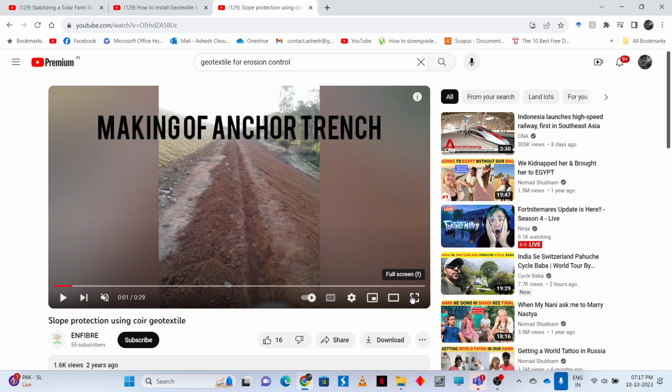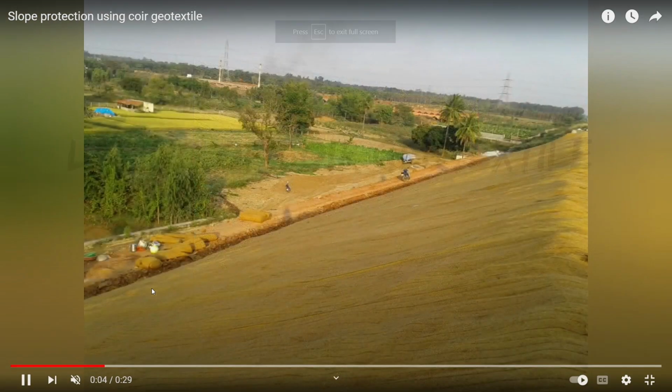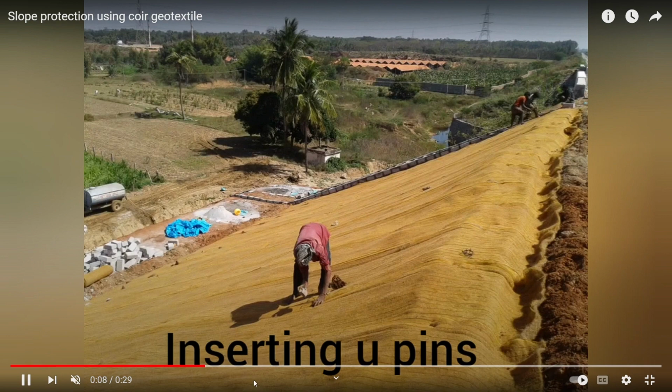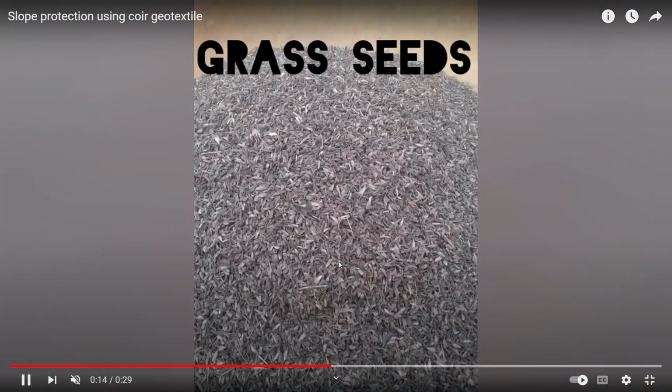And then you can see one more here, slope protection. This is the anchor trench. You can see this is a very big and vast slope. You have the geotextile, and this is the anchor trench. You put some amount of this geotextile into the trench and then cover it up, so that the geotextile does not slide downwards. We put the U shape and then cover the geotextile with soil on the slope.